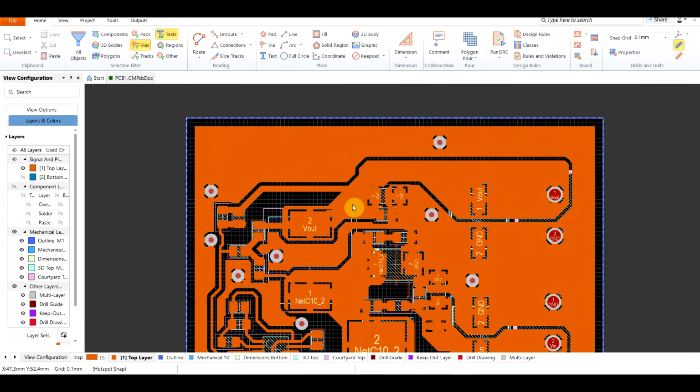So in the actual board that I ended up making, even though the entire output voltage net is quite large, the measurement resistor is connected close to the first output capacitor. So by applying this method, you're preventing less of the noise coming from the inductor to get pushed into the feedback line and the more filtered DC value to be sensed. Now, for relatively low current applications and short distances, this is almost always the approach that is taken.